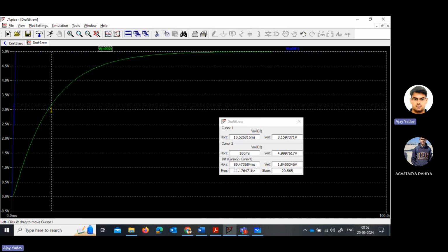It is almost near 10 millisecond, right? So when we assume a practical system where there is 1% rise time or fall time, because that will happen, you are able to obtain around 10 millisecond RC or time constant. So this is almost accurate.